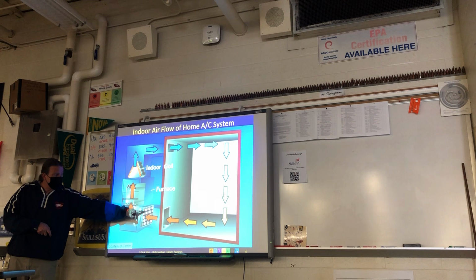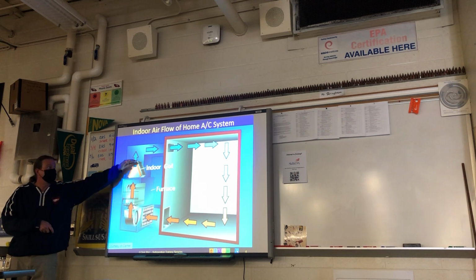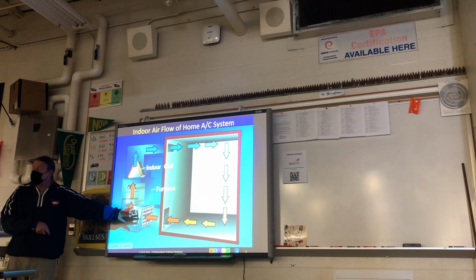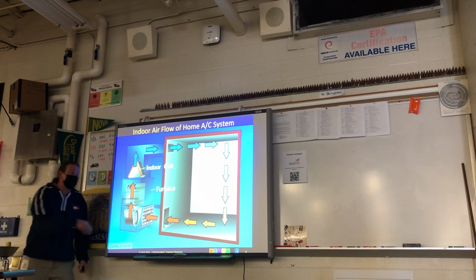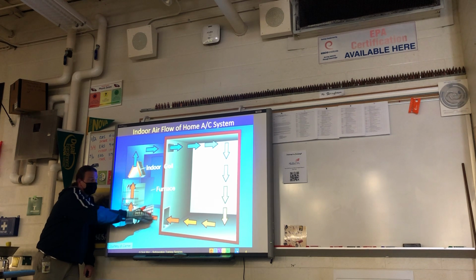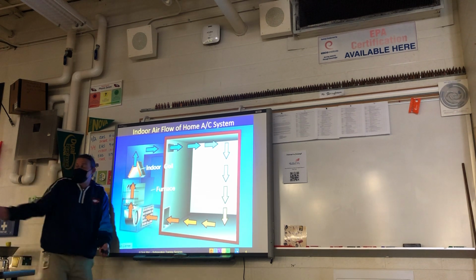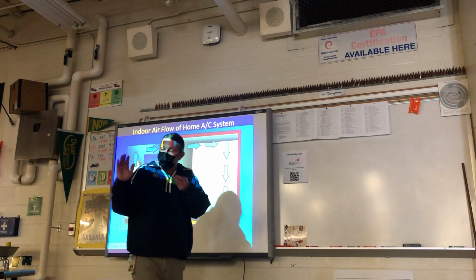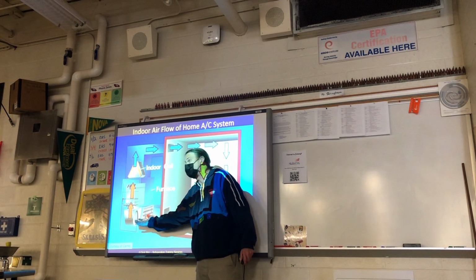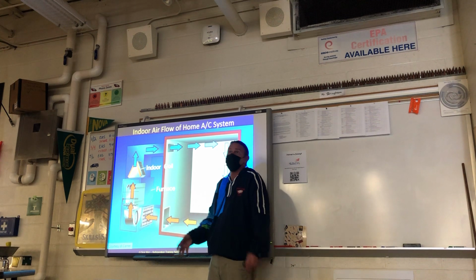And what's that right there? What do we want to protect the coil from getting? Filter. A filter, yeah, and that's got to be changed every 6 months. So a job you do when you first start out in the trade is nothing but going out to people's houses and trying to find their filter. It's going to be close to the return, okay? Then you do your maintenance, checking a bunch of stuff, making sure all the electrical connections are good. There used to be a thing where you oiled motors and changed belts, but they're all sealed now. There are beltless drive motors now.